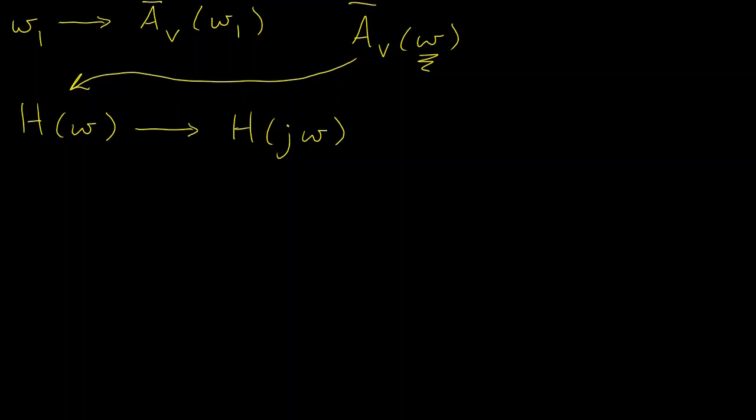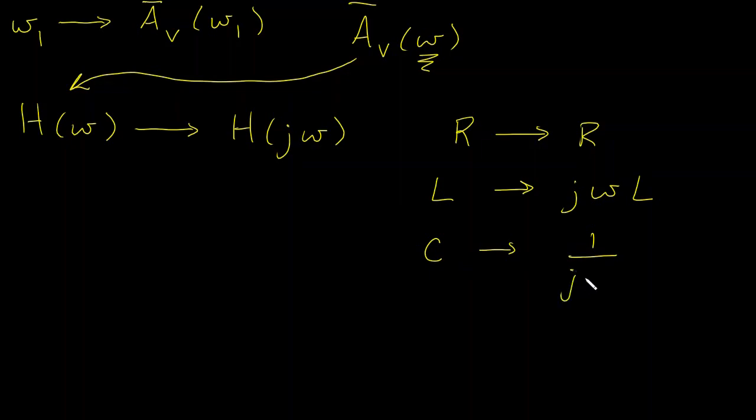It depends on how you treat it, obviously, because as we know, the impedance of a resistor is the resistance, and the impedance of the inductor, if we have L, becomes j omega L. And if we have a capacitor, then the impedance is 1 over j omega C, which equals negative j over omega C. Now, we might not want to always write it that way. We may want to leave it represented the first way when we build out the functional expression that determines the voltage gain of the circuit.